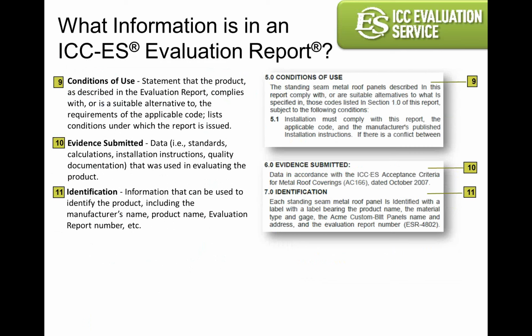I looked at the reports on 4 different EIFS manufacturers, and all of them state in the conditions of use paragraph that their product is not permitted in type 5 construction for occupancy groups R1, R2, R3, and R4. So that's a really critical thing: you can use it for other occupancy groups and other construction types, but you can't use it for a stick-built hotel.